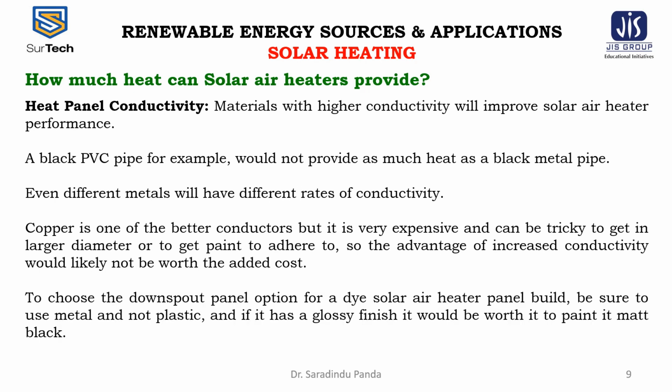To choose the downspout panel option for a DIY solar air heater panel build, be sure to use the metal and not plastic. And if it has a glossy finish, then it would be worth it to paint it matte black.